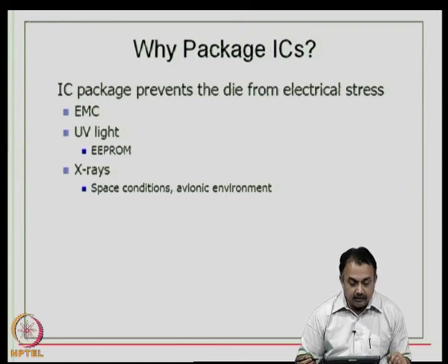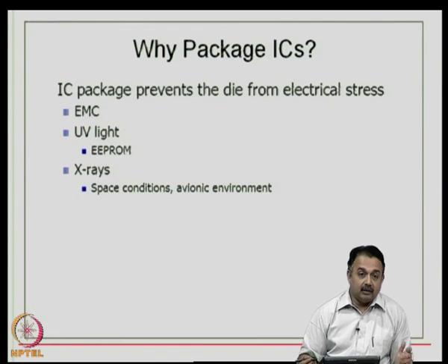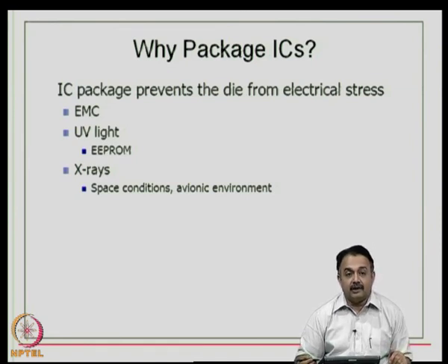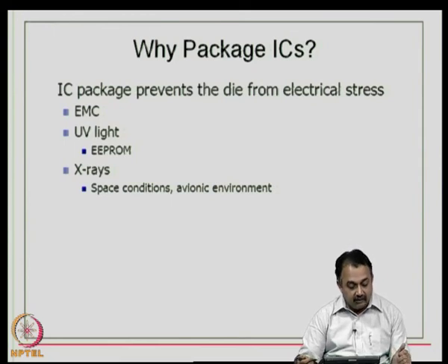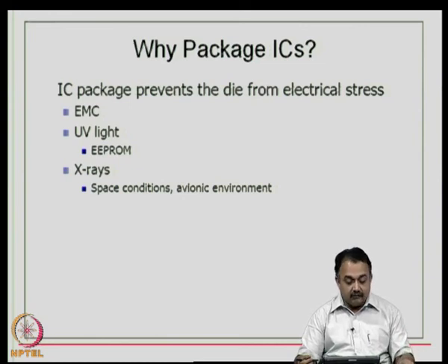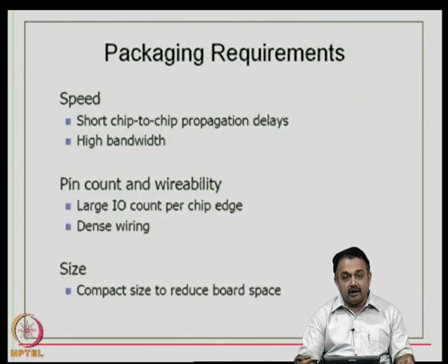Then if you are going to expose it to UV light either during programming like EEPROM or during the operation, if there is an exposure to UV light, then you can have electrical stress that can creep into the system and spoil your first level interconnects. Then X-rays like space conditions and avionic environment, these are areas where you can expect damage to the die. That is why it needs to be protected.